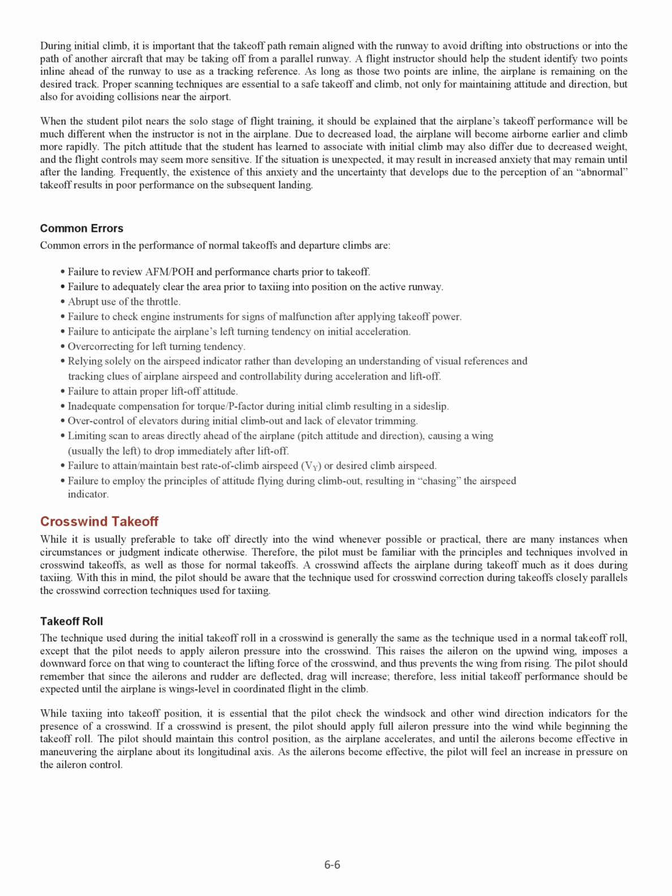overcontrol of elevators during initial climb-out and lack of elevator trimming, limiting scan to areas directly ahead of the airplane, pitch attitude and direction, causing a wing, usually the left, to drop immediately after liftoff. Failure to attain or maintain best rate of climb airspeed, Vy, or desired climb airspeed. Failure to employ the principles of attitude flying during climb-out, resulting in chasing the airspeed indicator.